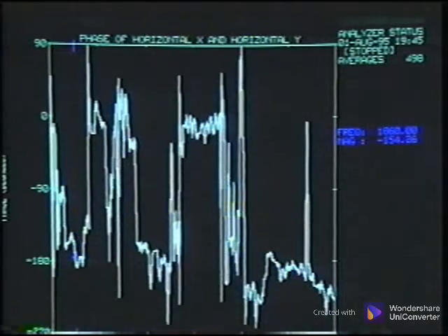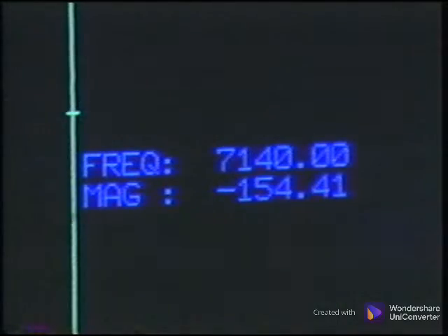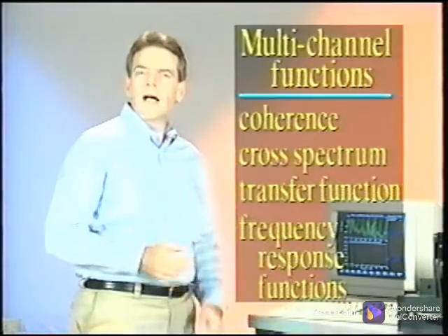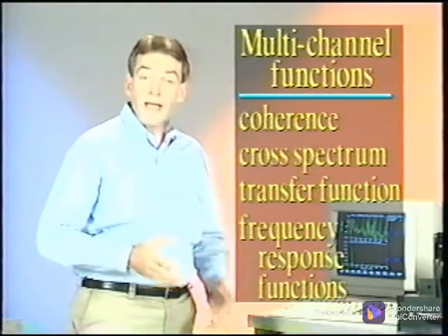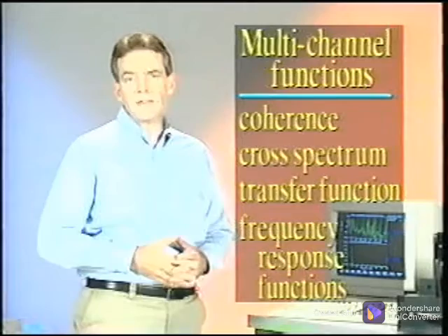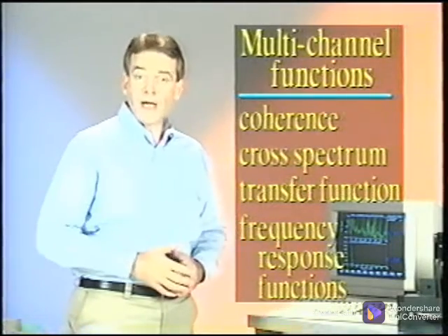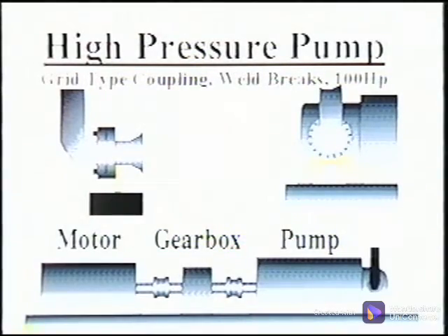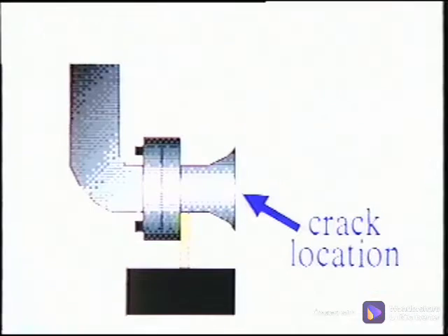The second difference is the multi-channel has the ability to look at any frequency of interest. Another advantage is the data is stored as spectral and waveform data, allowing you at your convenience to perform any analysis, including cross-channel phase, which is only one of many multi-channel functions. A case history involving multi-channel phase data to solve a vibration problem on a high-pressure centrifugal pump illustrates the value of phase analysis. The pump header repeatedly cracked, causing a shutdown of the manufacturing process.